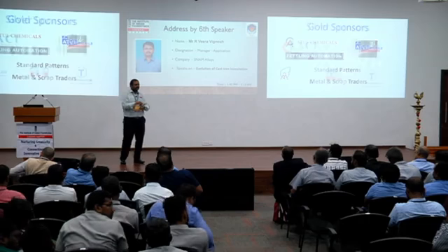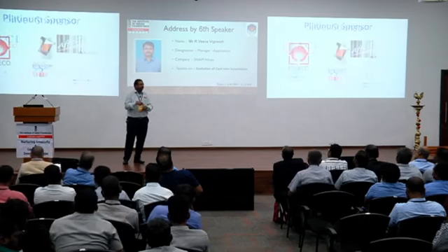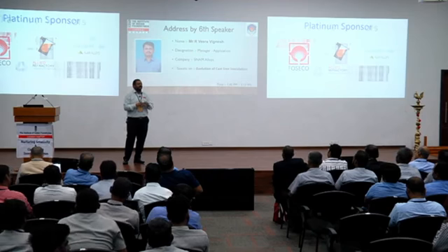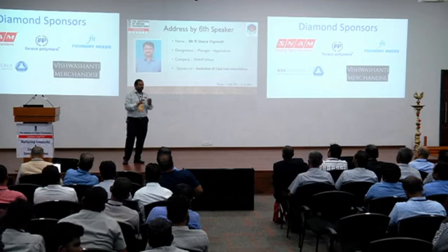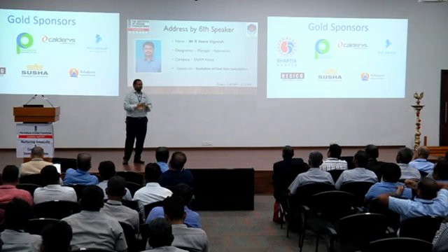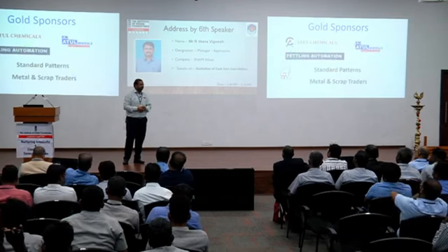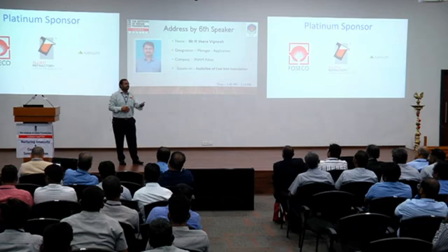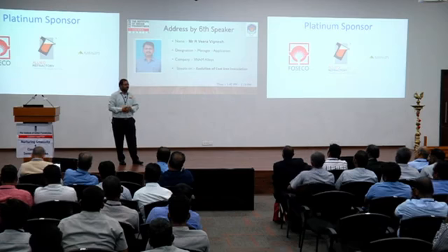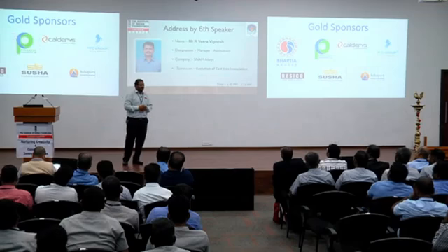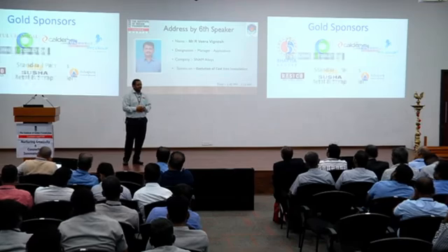Generally all these carbide forming elements will be located around the grain boundaries. So if we can ensure that our cooling rate of the casting is maintained such that the molybdenum carbides are not pushed towards the grain boundaries or sudden chilling does not happen, we can avoid the severity of molybdenum, chromium, vanadium, these carbide forming elements. There is usefulness of all these elements. These increase your high temperature creep resistance, what we call in engine blocks and CMO castings. But the network of all these compounds is dangerous. So inoculant does not have any part to do with that, sir. It is to do with the solidification pattern of the liquid metal in the casting, sir.